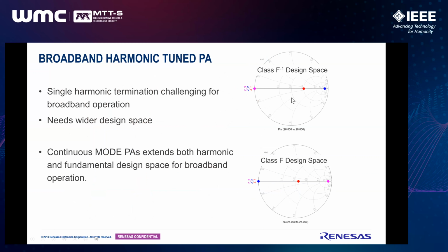Again, since we got all the current components and the voltage components, you can calculate the design space, like fundamental impedance, second harmonic impedance, and third harmonic impedance is going to be short-circuited. And that way we can have voltage shaping, and current remains still the same. Since there is no change from the real components of the current and voltage, still all the class BJ termination has the similar efficiency like class B.